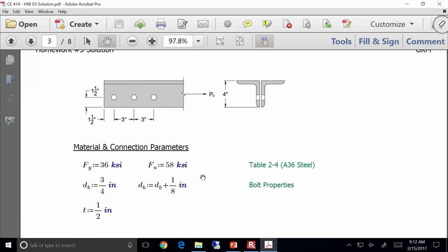The thickness and stuff. Well, okay, what's the name of the angle? So they're L 4.5 by 3.5 by what? All right, the 4.5 and the 3.5 are the lengths of the legs, and the 1/2 is the thickness. Not for angles. And maybe I should have cleared that up earlier, but for angles, it's a 1/2 inch. If you go to table 1.7 where you're just looking at each individual angle, one of the things it will not report is a thickness. They're rolled to be 1/4 inch, 3/8, 1/2. That is a reasonable concern. I could appreciate that.